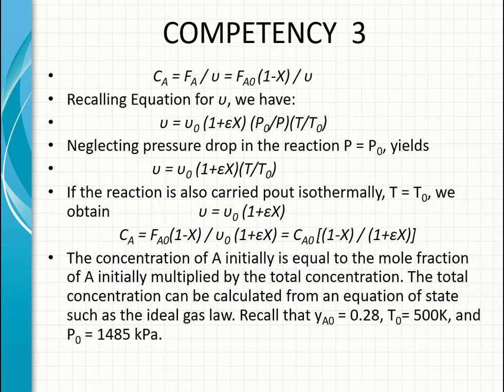So the concentration of A is going to be the molar flow rate of A, FA, divided by the volumetric flow rate v. And this is equal to FA0 times 1 minus X divided by the volumetric flow rate v.